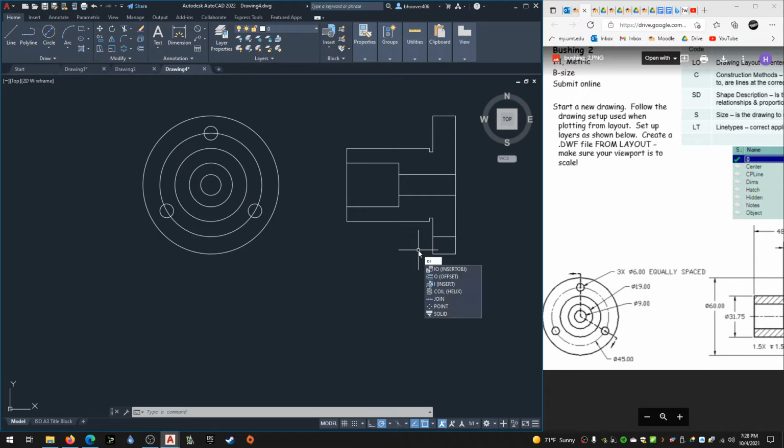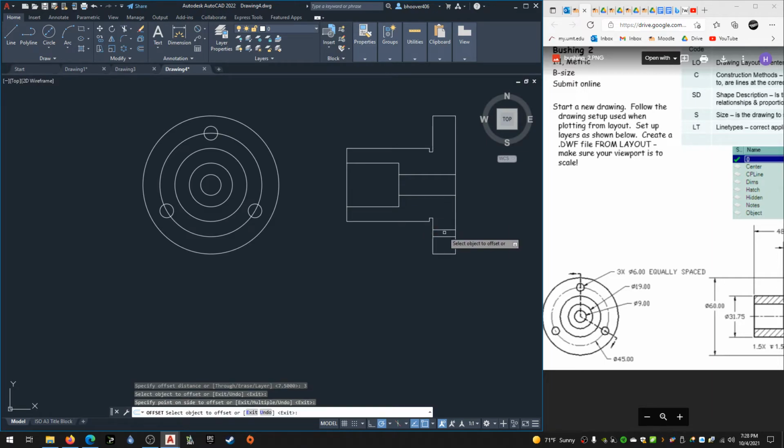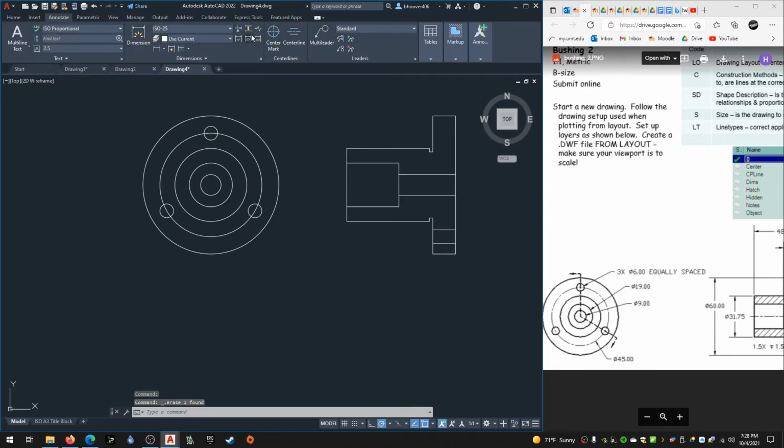So then I go offset, and this is going to be a 3-inch radius because I'm going to go above and below like that. And I can delete that and go to annotate, center line, click my 2 lines. I get my center line, and now I can mirror to the top, here to here, say no. And there are my holes.